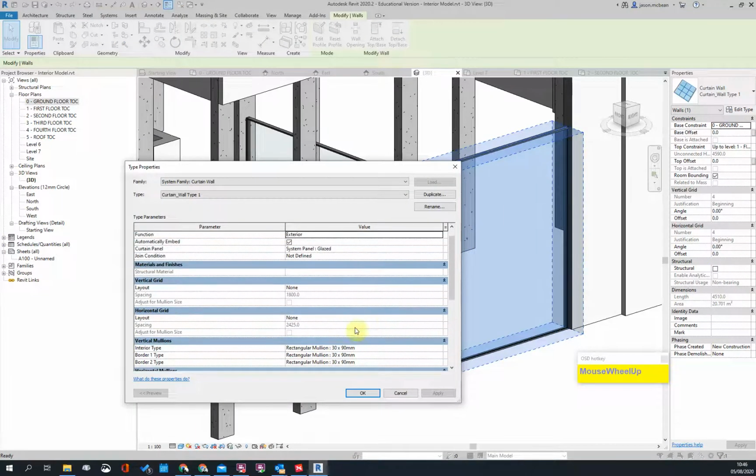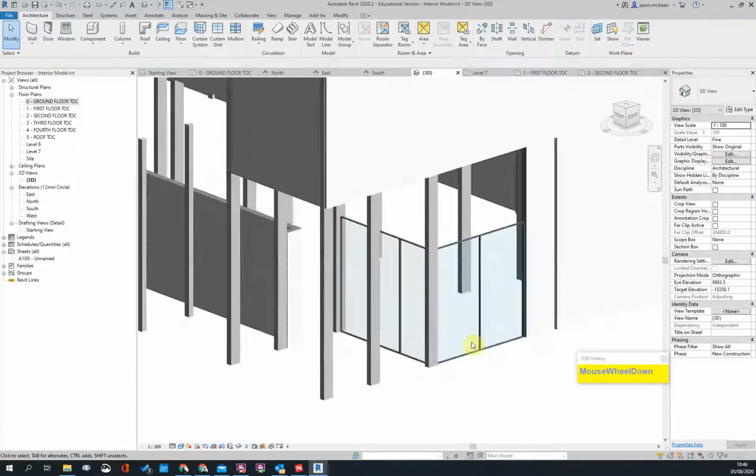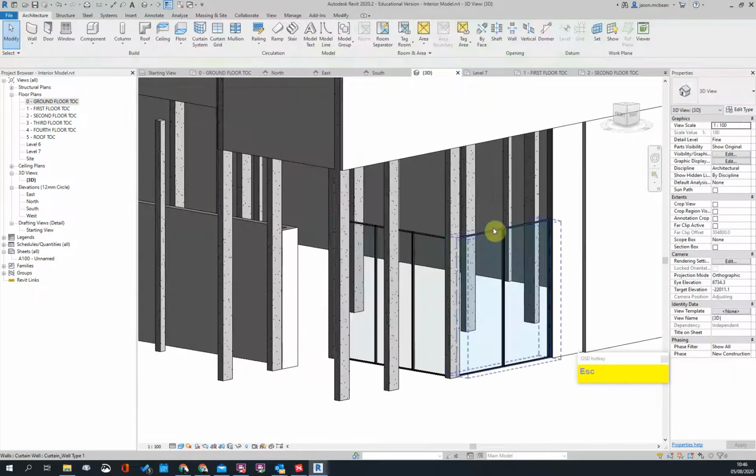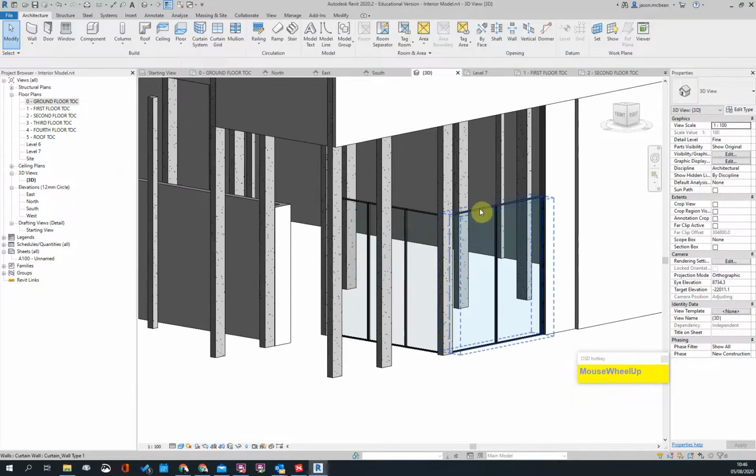It's pre-set up. The mullions are pre-set up. Just remember they work in a grid system. I need to introduce some vertical grids. So fixed spacing, it's a maximum spacing that we work with. And those are usually at, it depends. We usually use 1800 or they're usually 2400. Okay. Press apply. But this we can customize as we go along. I just want to get the basics in play. Okay. All right. That works well for me.